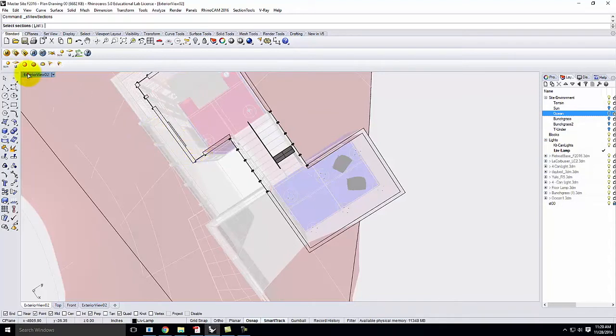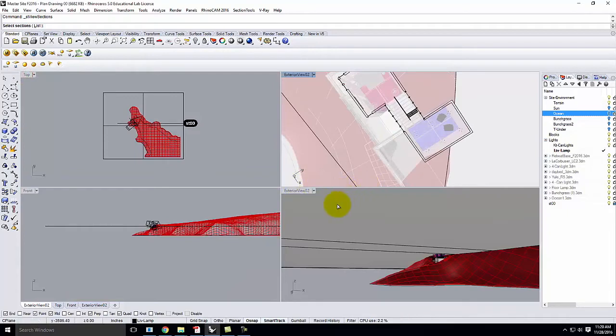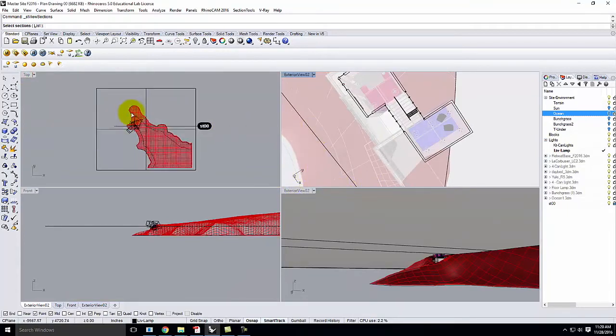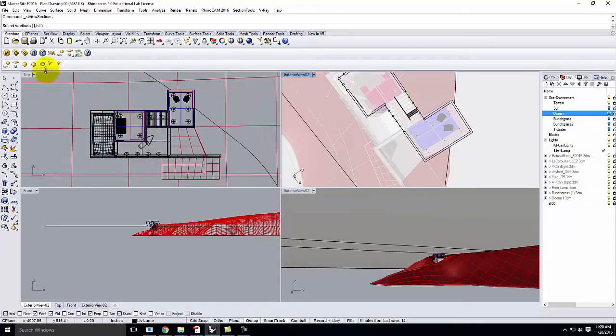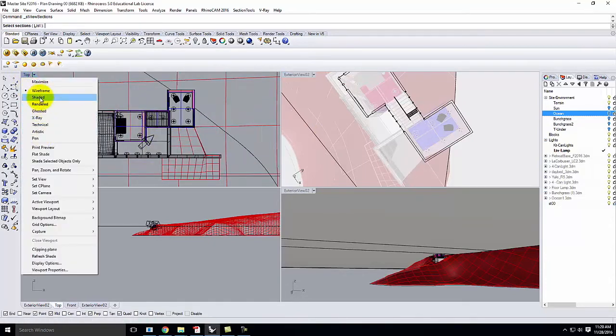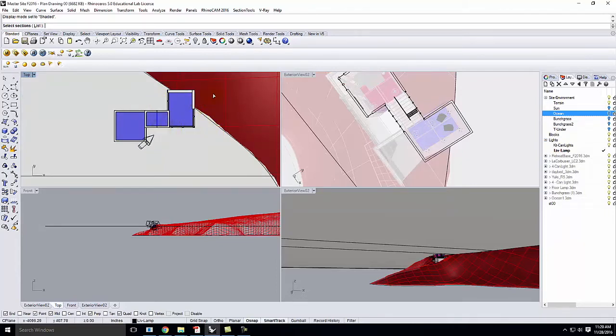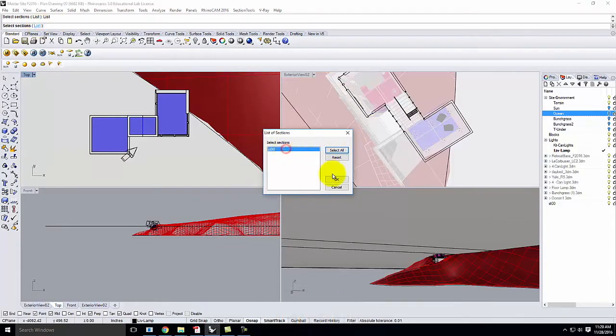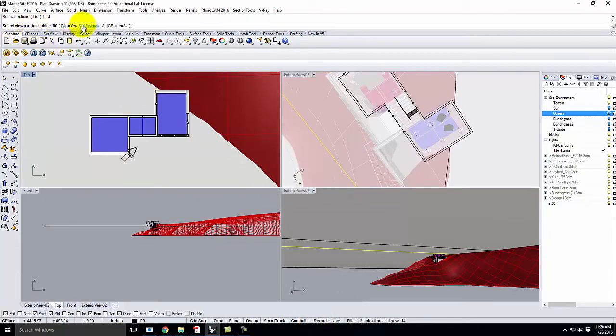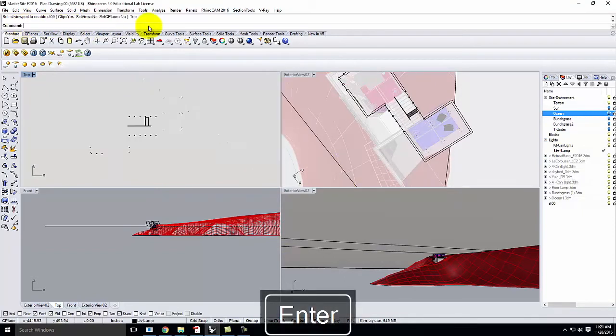Okay, so now it's a matter of actually setting up a true plan view. So we could look at it in the top view, something like that. I'm going to go ahead and show this as shaded mode. And then I'll type STView, STView sections. And I want to see ST00. And I want to show it in the top view.